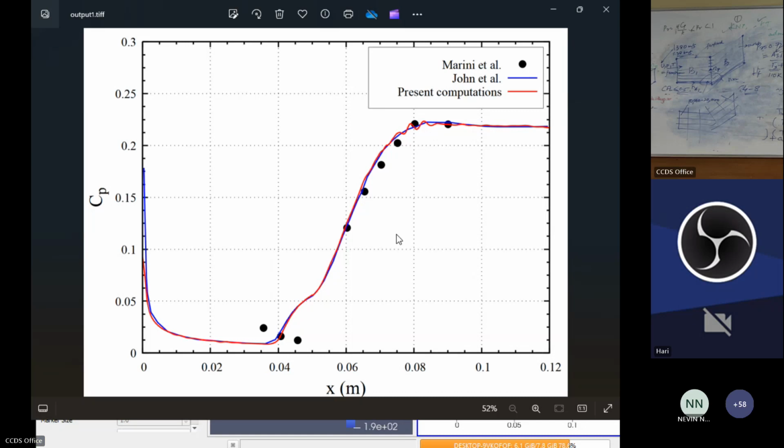So you can now hopefully run a compressible flow simulation using the rhoCentralFoam solver. There are certain customized solvers also available. If you go to GitHub, you can try to compile the solver, but you need to install the specific version which they have coded. So it is up to you how you proceed further. This was the basic glimpse of what a compressible flow solver is all about. If you have any queries, you are free to ask me, and then we can wind up the session.